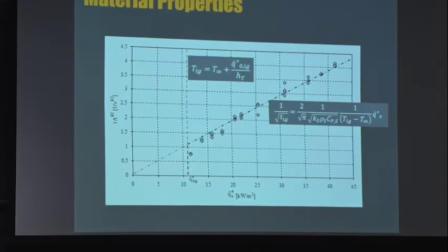line here. Okay? So in one of the papers that I gave you, I put the two solutions so you can see. So this is the low heat flux, and this is the high heat flux solution. Okay? But the fit has to go through 0, but for the data that you're going to use, you have to privilege the high heat fluxes. So FM Global will say that you have to go above 30, but most people will generally go above 20, and that still gives you fairly good fit with the theory.